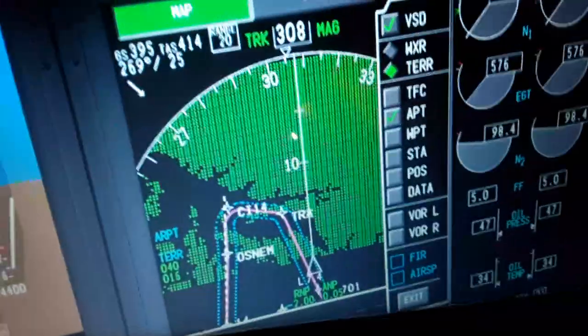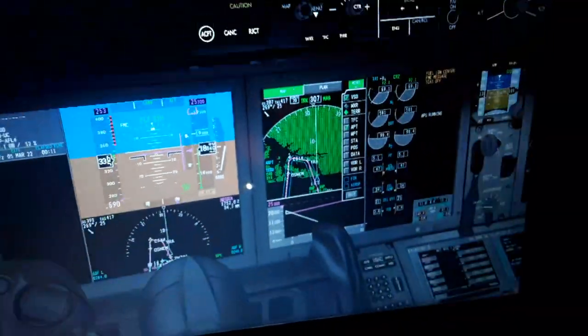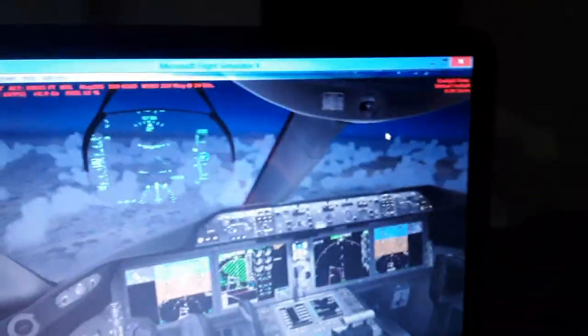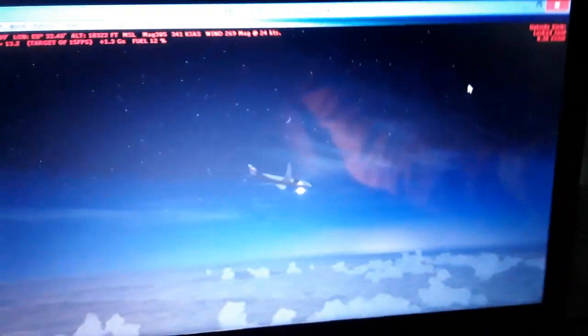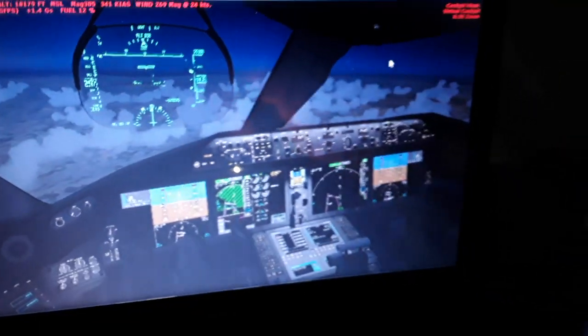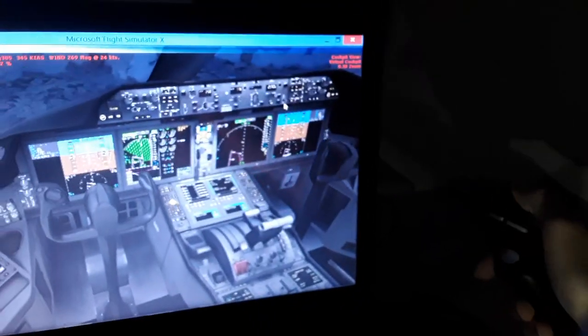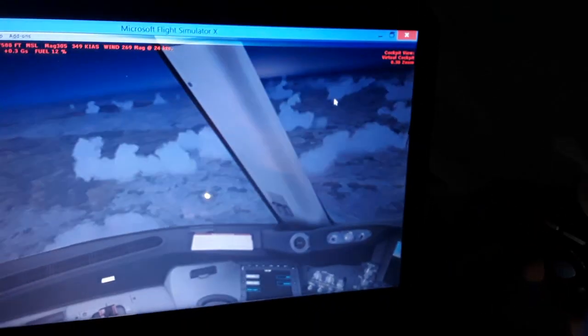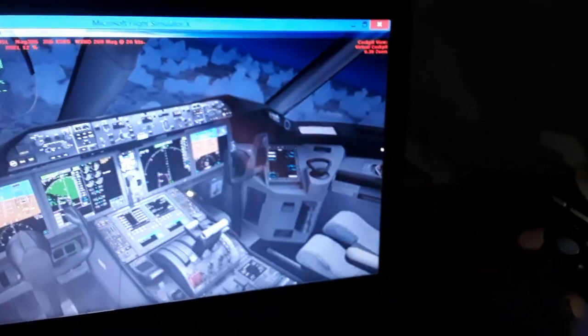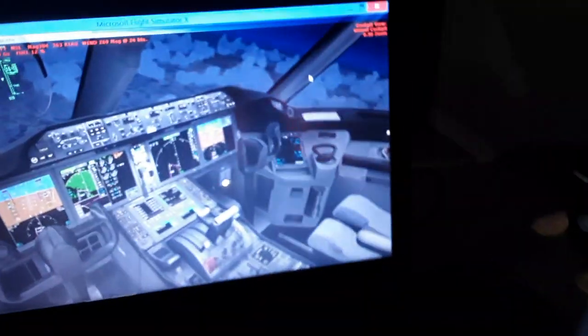Also in this screen, next waypoint, ground speed. So we leave behind the waypoint and we go for the next one. We keep descending. We have transition altitude over here. Increase rate of descent, idle thrust. And start off for the turn now, for going into the airport.